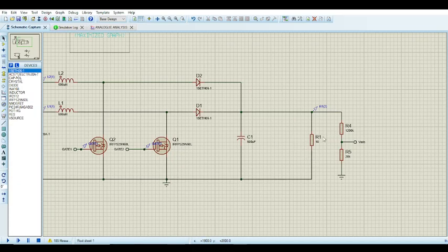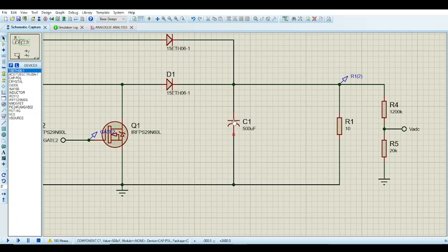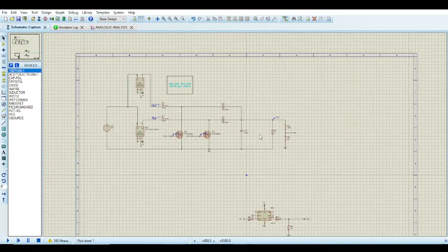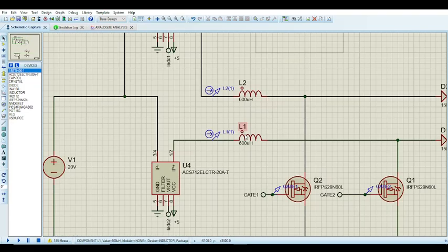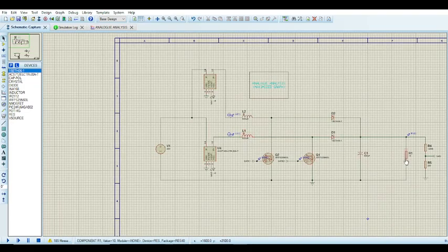And obviously, output, this is just a load. You might have any other type of load. And if your load is not switching, you essentially don't need a capacitance this high. If it's a switching load, you need something this high to counteract that. But in a continuous load, lower than that should be fine.